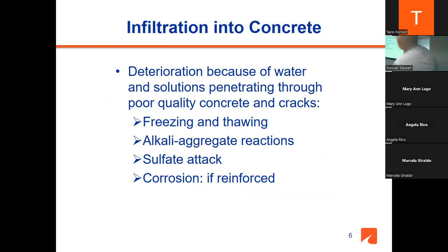Now, what we find out in real life is that when we have infiltration into concrete, it's no longer dry, things are penetrating into concrete. If we have, for example, water and solutions penetrate into concrete, then we would have some problems, some distress mechanisms. How do solutions get into concrete? They get in through poor quality concrete, the permeability of the concrete, and also through the cracks. If the cracks are wide, then they will let in the solutions. So it's important to keep the cracks tight, and we'll talk a little bit about that.